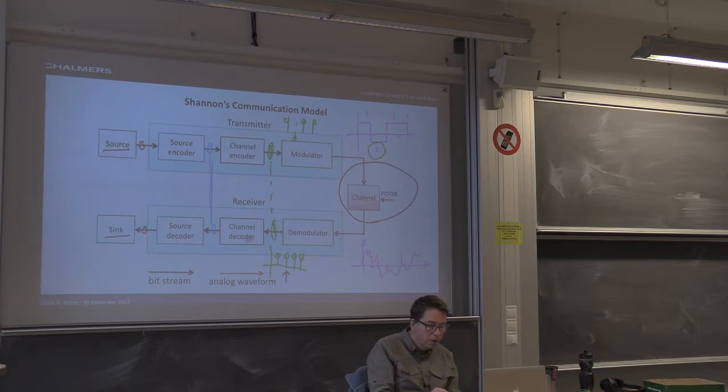So the purpose of the channel decoder is to inspect these bits and see, does this make sense? Because there are some rules in this channel encoder that permit some of these sequences and disallow some other sequences. If everything works well, the channel decoder can say, aha, this bit looks very funny, I don't believe this. So let me flip that bit and see if that works. And then it flips that bit and says, now it makes sense. So let me correct that bit and hope that this was actually the error that occurred. And it happens to be in this case.